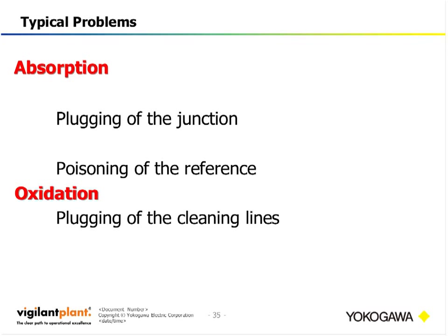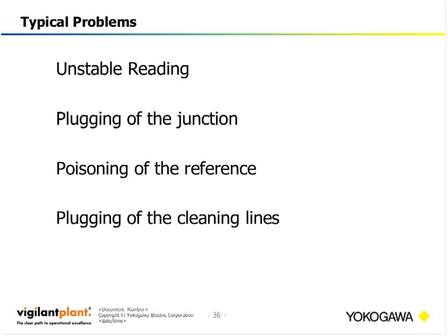Here, the typical problem they see is that the calcium compounds produced in the scrubbers tend to accumulate in the circulation loops and cause a buildup of scale. The lime can cause scaling on the pH electrode, which affects the measurement. To ensure accurate measurement, frequent cleaning of the electrodes with acid was required, which adds both maintenance workload and cost. So having accurate, reliable pH control is necessary not only to control the feed of the lime and limestone, but also to forestall the start of scaling, because it's easier to prevent it than it is to remove it once it happens.